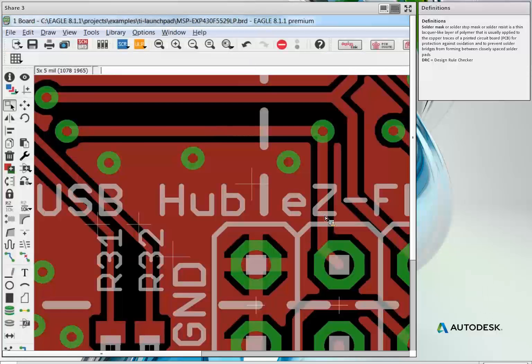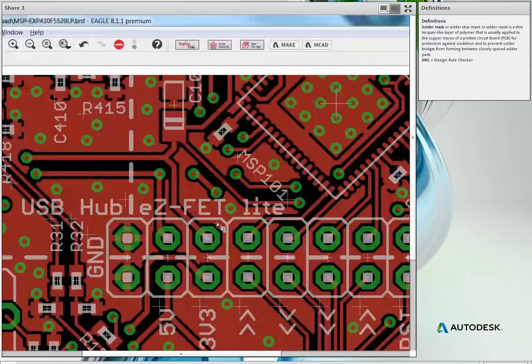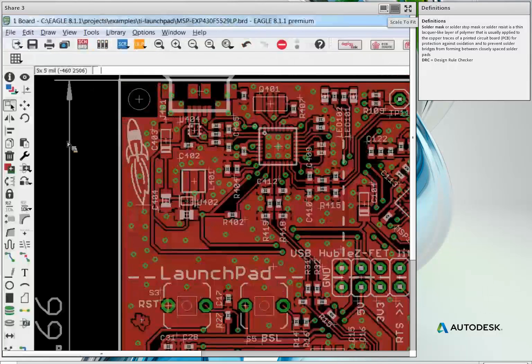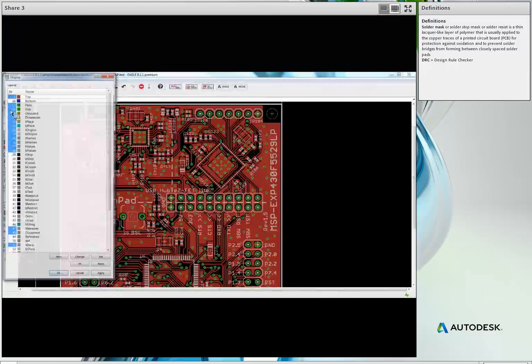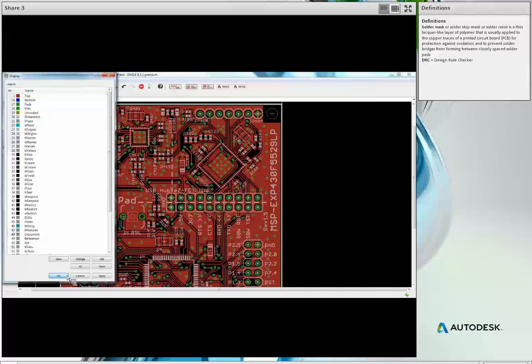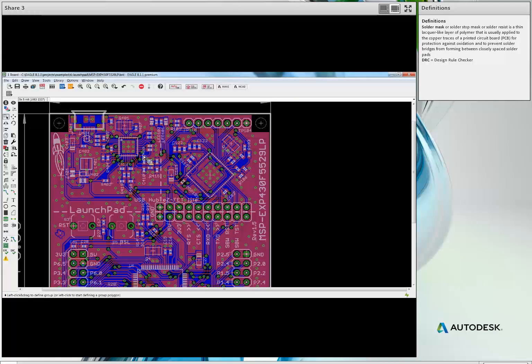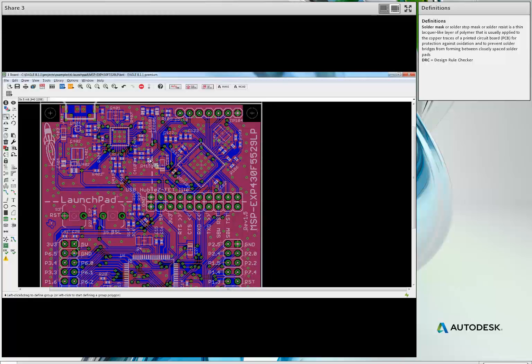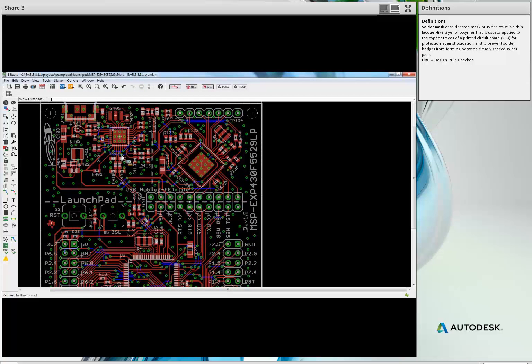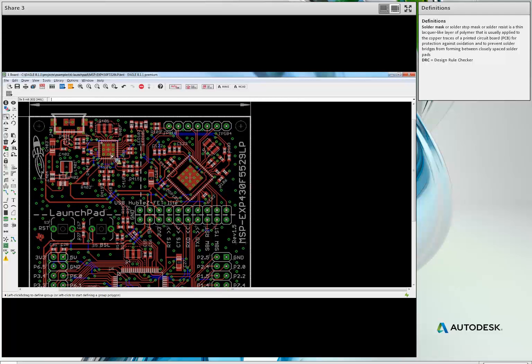Okay, so this is the TI Launchpad. It's a 4-layer board, a 2-layer board, I'm sorry. And turn on the bottom layer as well. You notice that I'm not using the blending, so I can get the solid colors throughout. I've created an alias that way I can rat's nest my board without having the polygons. That way it makes it a little bit easier for me to take a look at the board. So I just got rid of the polygons. It's not really a big deal.